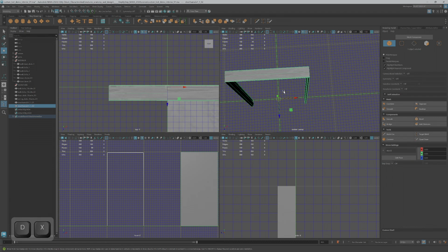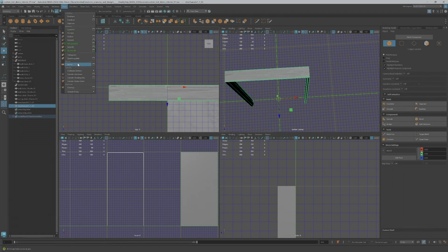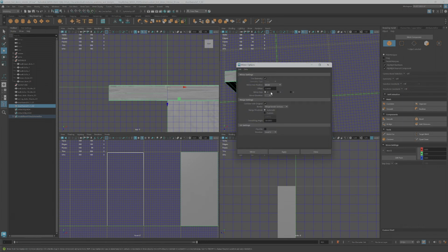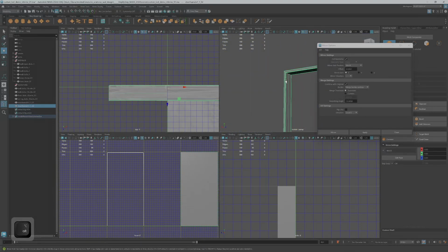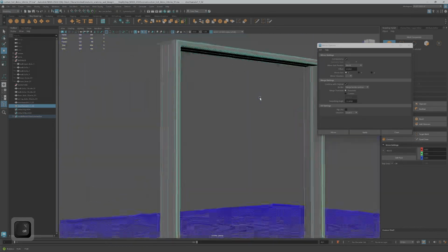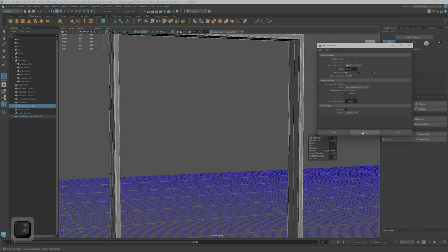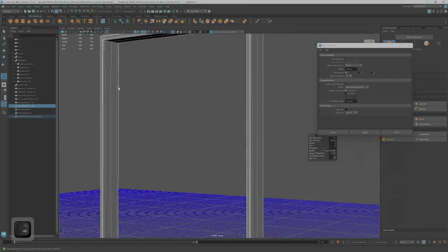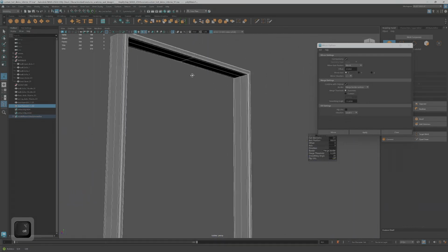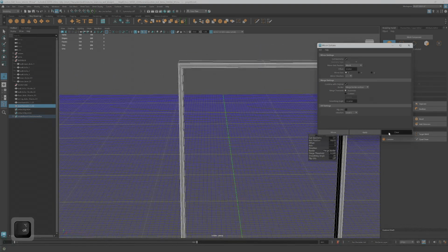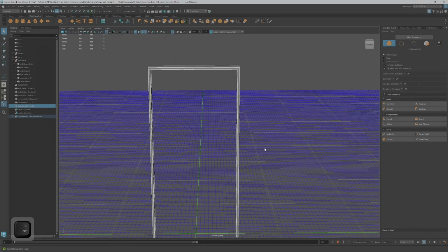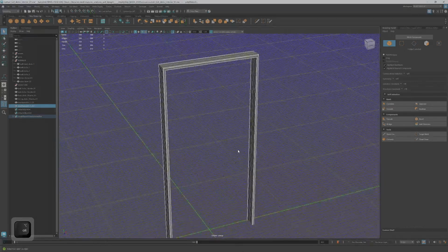There we go, just like that. And we'll go to the mesh tool and we'll use the mirror across X. And double check, it should fix it. Let's see if that, yeah, so now the good side has been mirrored over to the other side, and you have an edge lip cut in the middle, which is totally fine. We're not doing super low poly yet, and you can end the tool by hitting the Q button.